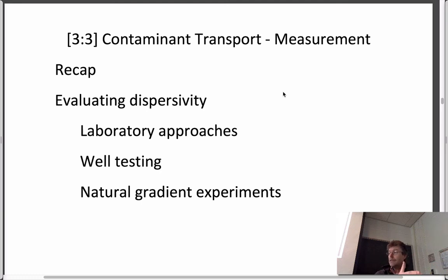One is advection, where it physically gets carried from point A to B on the back of the water that's traveling downstream. And at the same time, on that background, as it traverses from one location to another, it is able to spread by one of two mechanisms. The first and the slowest is by molecular diffusion, which is just Brownian motion, the same as putting ink in water or ink in milk, as we've talked about. And another mechanism, which is mechanical mixing, hydrodynamic dispersion, which looks just like the behavior we get from diffusion.